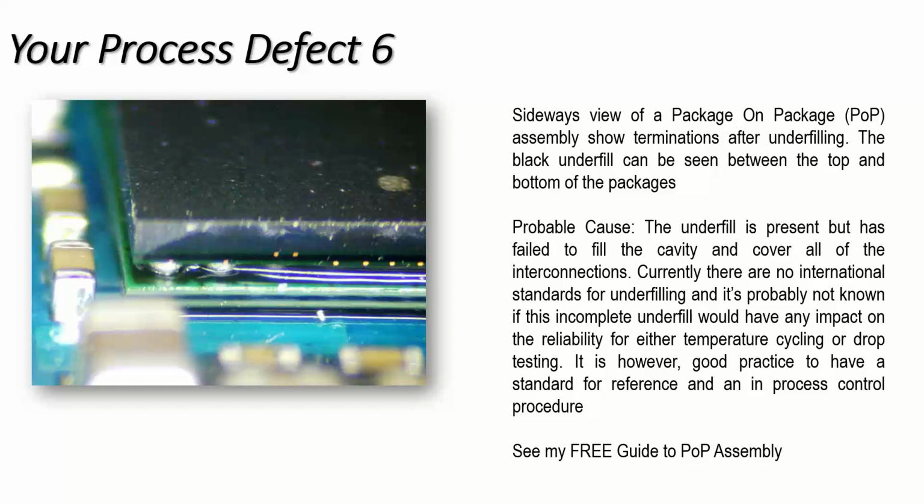I've done some trials on these with drop testing, and provided you've got a fairly large percentage coverage both on the bottom and on the top, you still get a benefit. So where you might have 1 or 2 balls exposed like this, I have not necessarily seen any issues. You don't get 50% failures because you've got a few balls not covered. There's not really any standards for this.